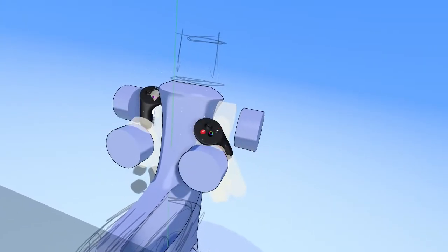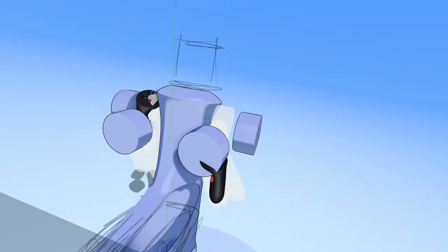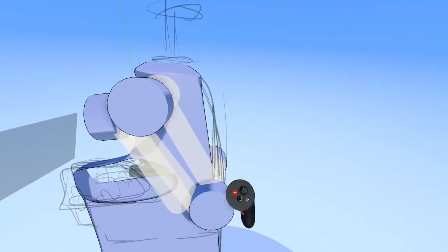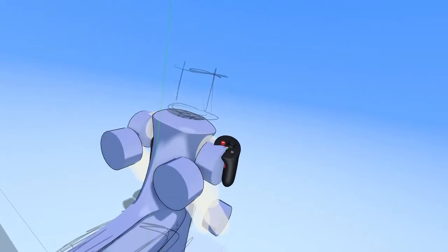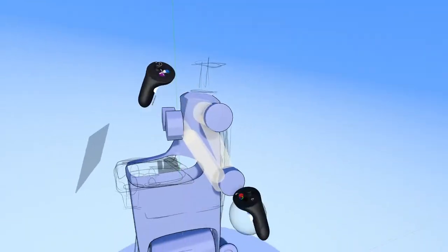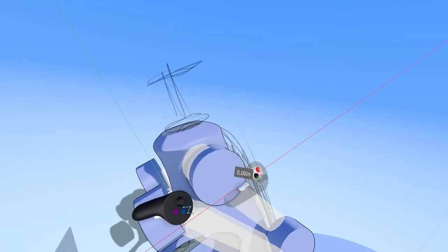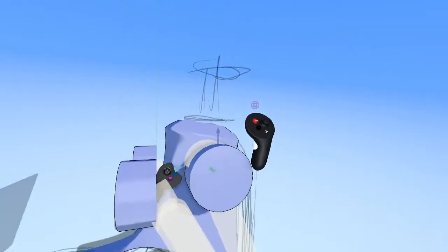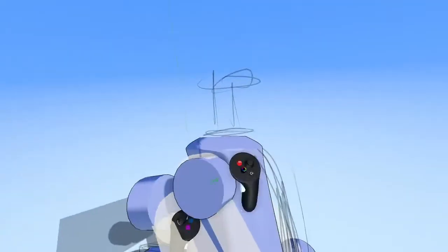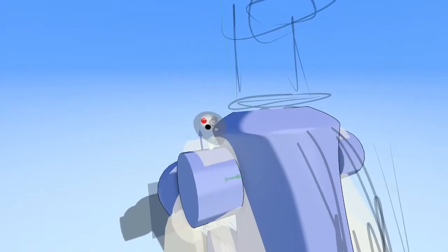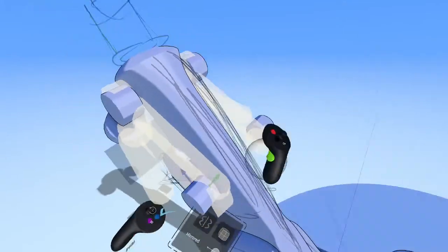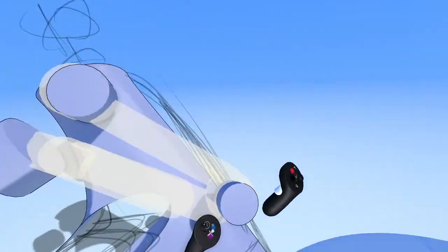Let's duplicate it, twist that so that it's facing the right way for that part of the arm. And then duplicate it one more time down for the elbow. So we have the shoulder, the elbow, and the wrist here. Now we can turn off the grid because we've placed it exactly the way we want it. And because we left it as a primitive shape, we can still adjust the general size of the shoulder like this with these 2 arrows. And use Smart Move to move it along an axis.